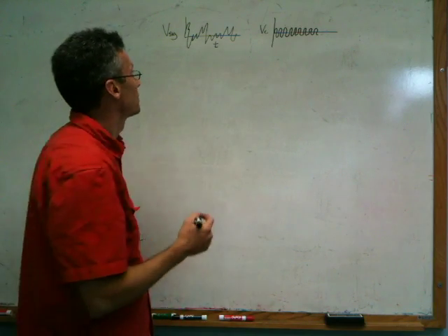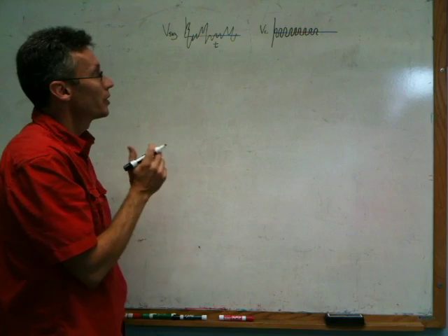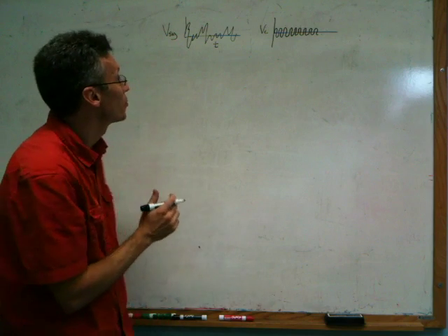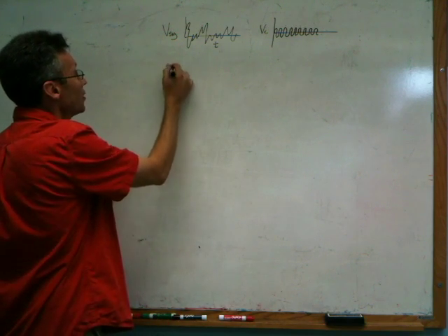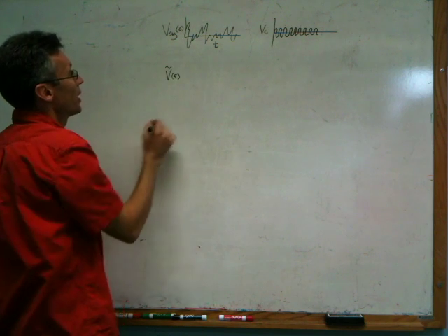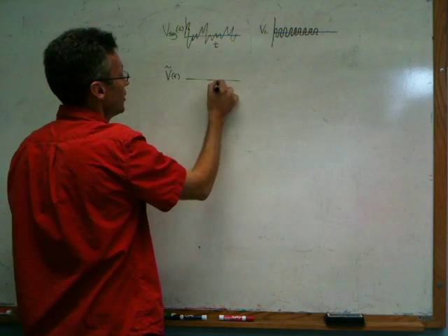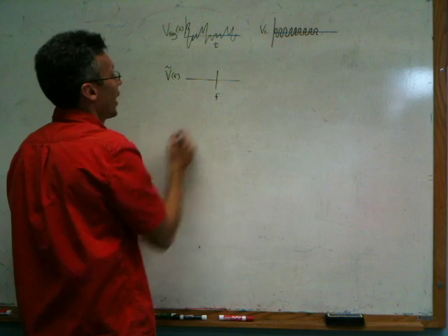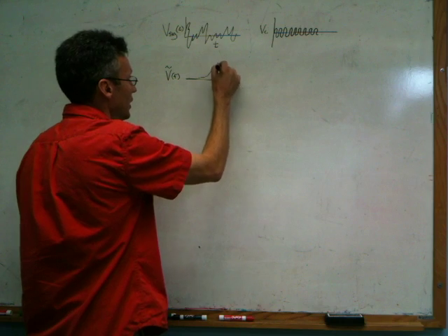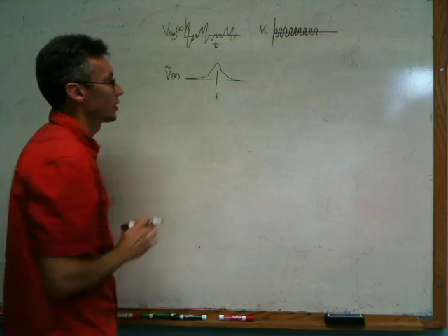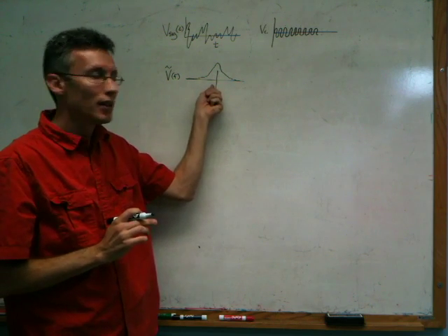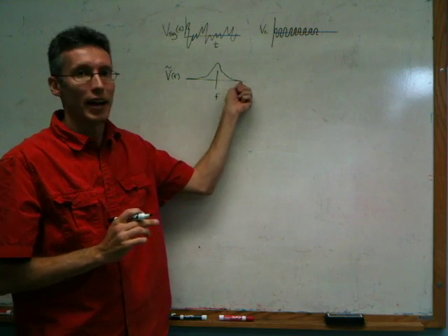be transmitted on. So in order to follow through all the steps in the modulation and demodulation scheme, it's really useful to look at the frequency components of these signals. So if I take the Fourier transform of this signal, I can plot the spectral content. And a typical signal is going to have most of its spectral content near DC, with less and less at higher and higher frequencies.